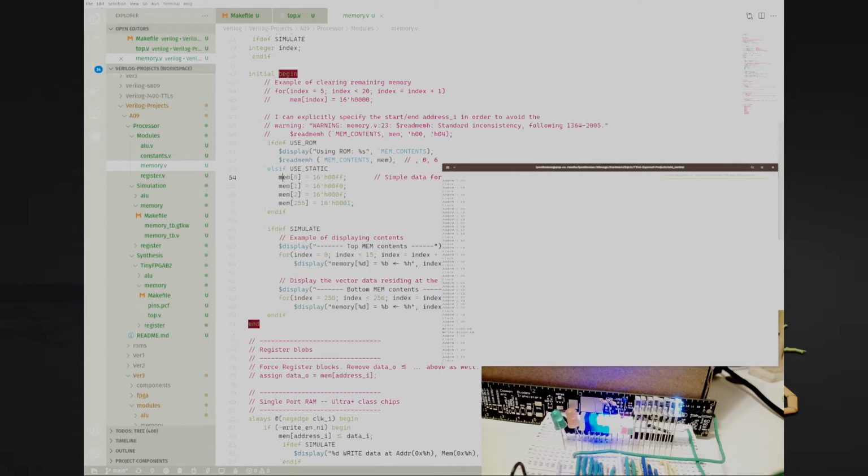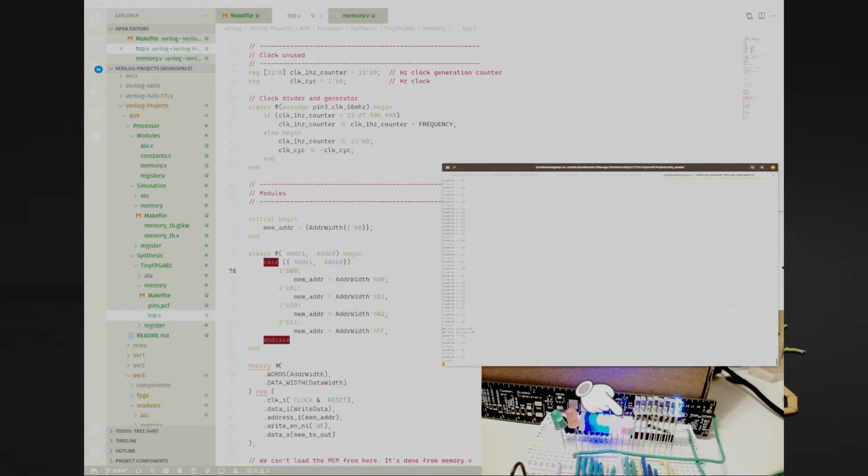We'll set our address back to 00. So we'll come back over here and we'll hit the A key and hit X, and they all went high. But now I'm going to hit my W key, and that's going to set the write enable low. So I set that low, I hit the X key again, and guess what? We just wrote a 5.5 to that memory location. Now I'm going to turn the write enable off, which highlights the LED again, and clock it, and nothing will happen. Why did it write 5.5 to there?